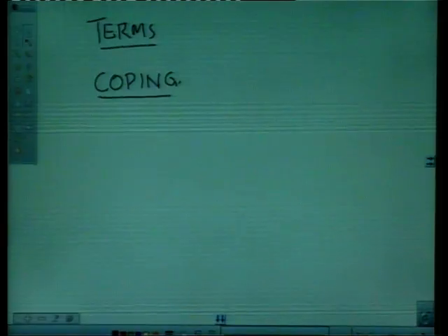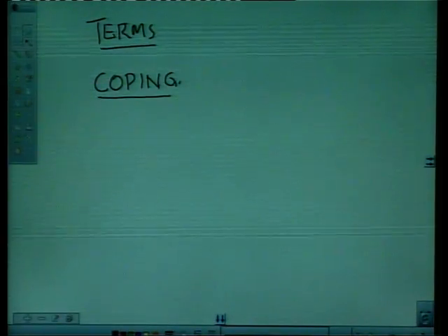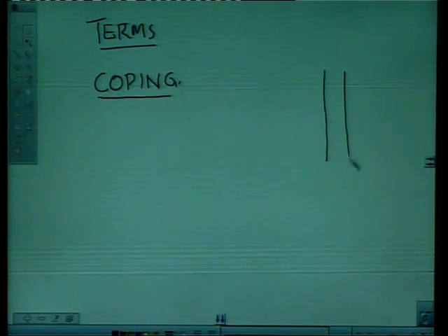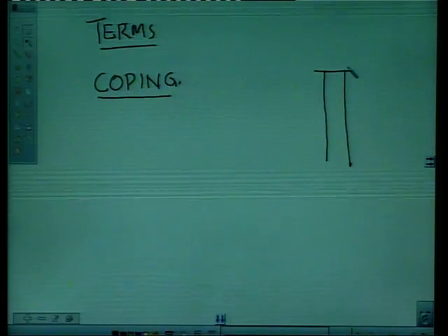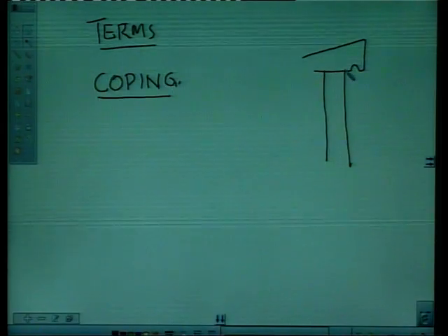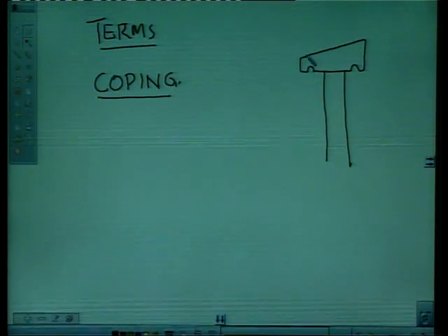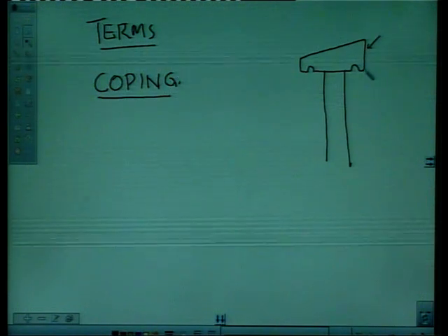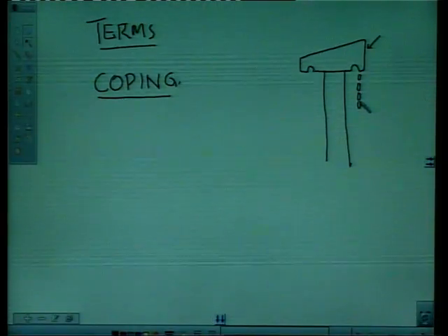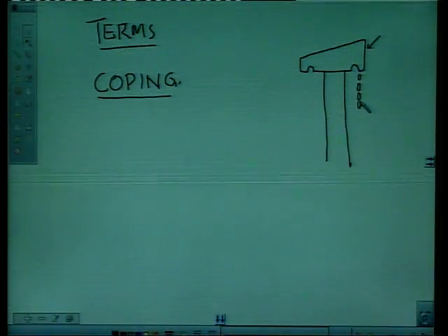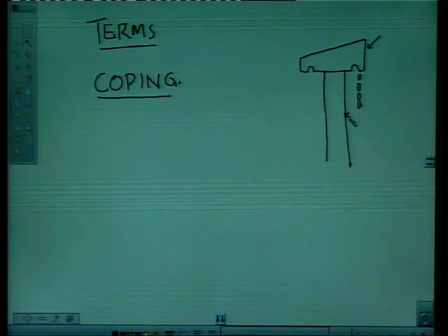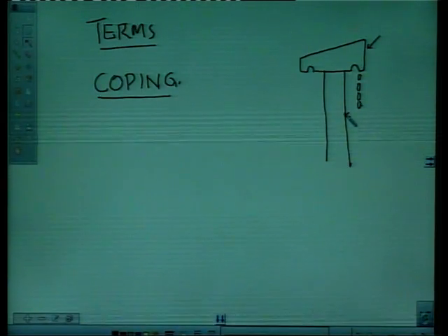Coping is the top of the wall, provided with a throat to prevent rainwater. So here I have a parapet wall, and this is a coping of big stone made like this one, and rainwater comes here and it trickles down from this throat. So rain does not wet this inner wall. So this is throating which is done, and this is my parapet wall.